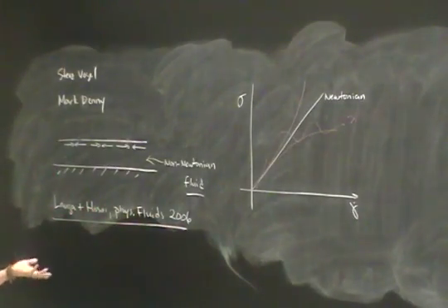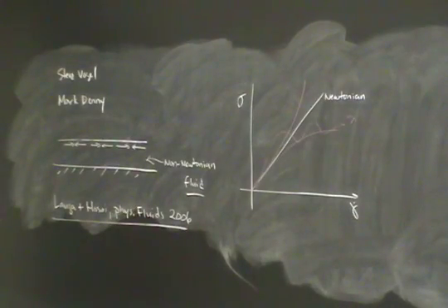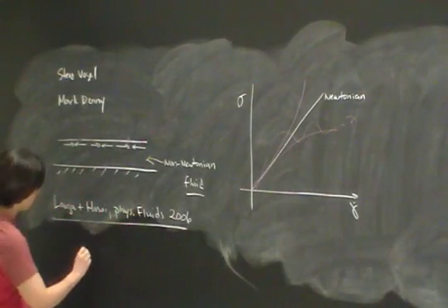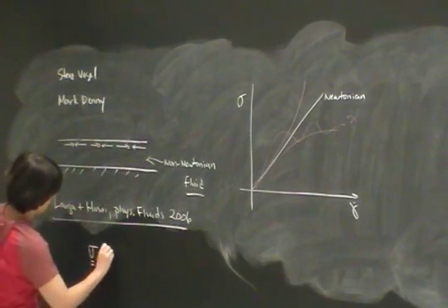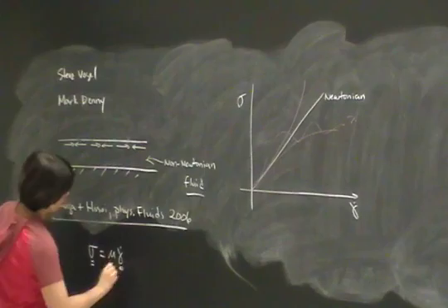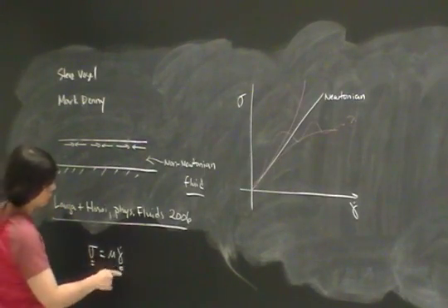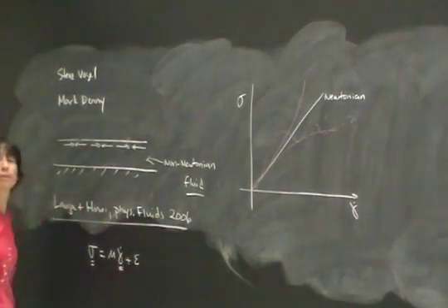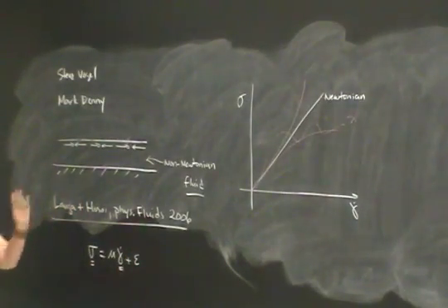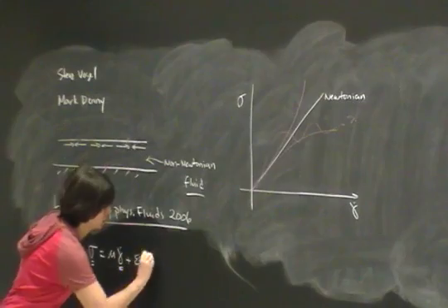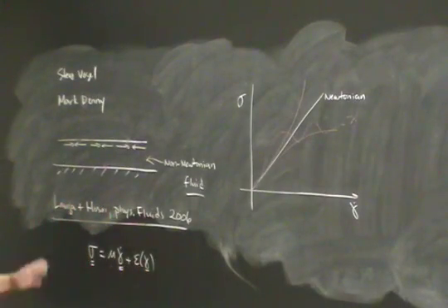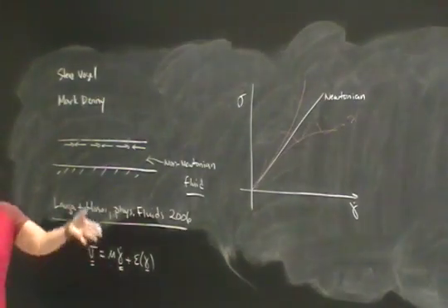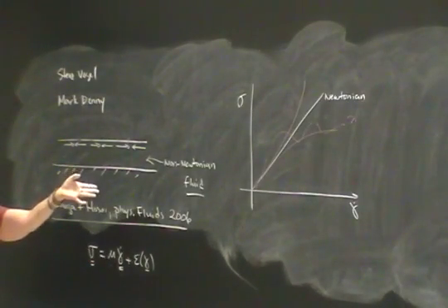It's again a thin film calculation, only now instead of having a Newtonian constitutive relationship, where my stress is proportional to my strain rate, Eric now perturbed that to put a little bit of perturbation on it, so you have something that's some functional of the strain rate. This is a small perturbation, and then you just go through a calculation similar to what we just did with a thin film.